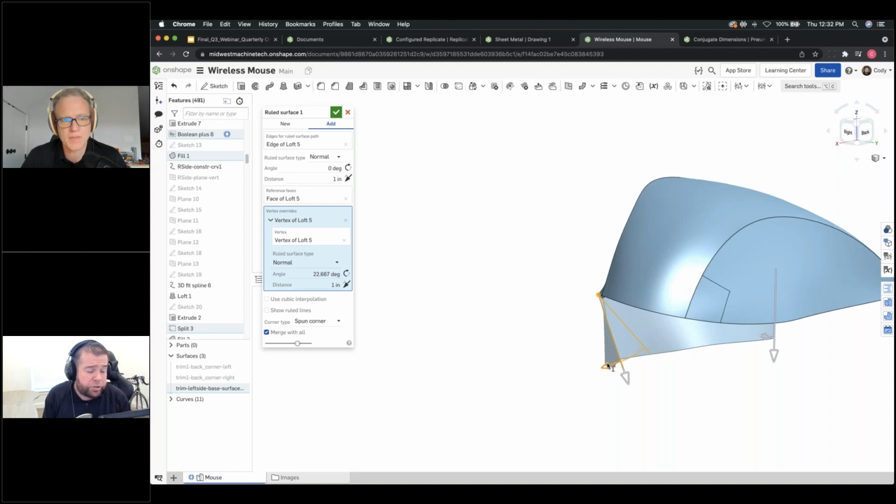And it's not just the ability to rotate, it's also the ability to extend the surface out further or pull the surface back. You can grab the arrow and do both of those things. You can even transition between different ruled surface types in each of these transitions. So really cool. The flexibility, the ability to grab and manipulate that surface is something that's been highly requested. Prior to this, you couldn't really do this with a sweep. It would have been a complex thing to do with a loft. It's a few clicks with a ruled surface. So that's what really makes it the most powerful.